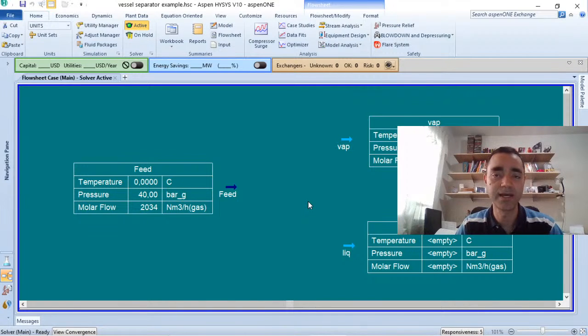And because of that, I have a heat exchanger, and it is a shell and tube heat exchanger with the shell using hot water to do the heating of this gas in order that I can vaporize the condensates that were formed during the operations. If the heat exchanger is working well, there is no problem, I will always be delivering gas to the customer.